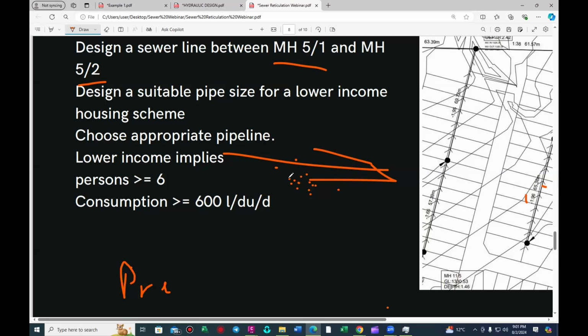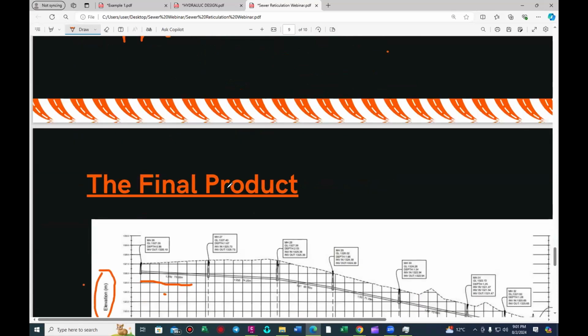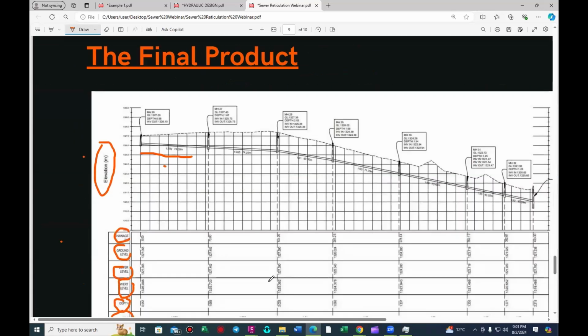And it can also cause scouring for our manholes and our pipe. It bends. So I've never designed a sewer system that reaches 3 meters per second. Even if you include your pump main station, this is where maybe you've got the danger of hitting high velocities like these ones, but they always have to be below 3 meters per second so that we don't have scouring, and also so that we don't have water jetting that leaves your solids behind.